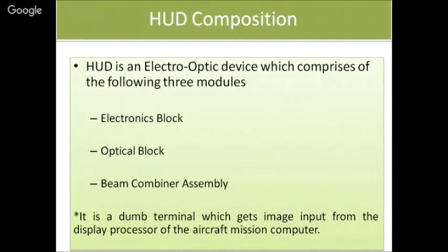We are using a DSP processor for inbuilt symbology generation only. Otherwise, we get XYZ information. Our requirements in the CRT need single-ended signals. So basically, we convert it into single-ended, and then other processing we do on a signal processing card, and finally V2I conversion is done through certain power amplifiers, and then it is displayed onto the CRT.